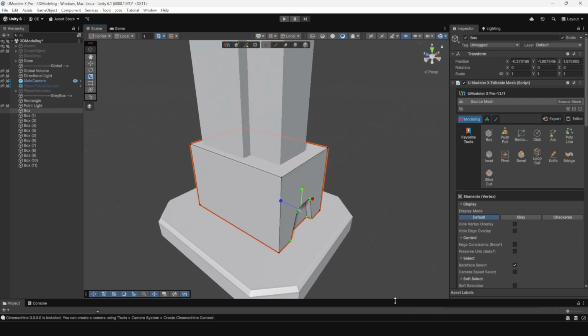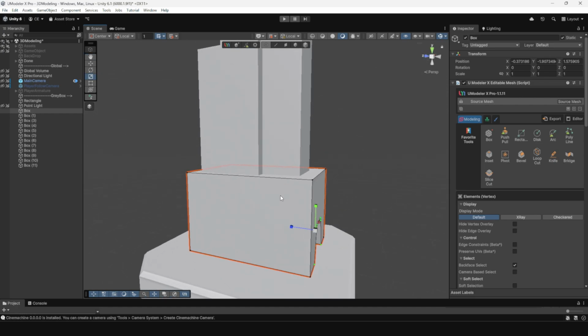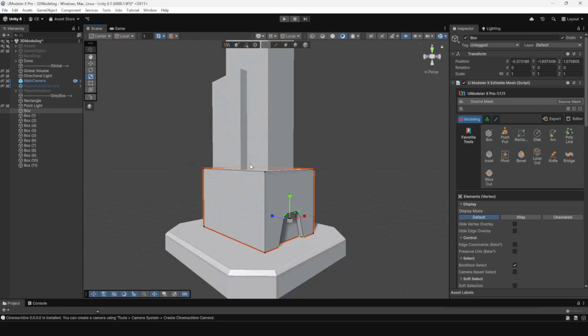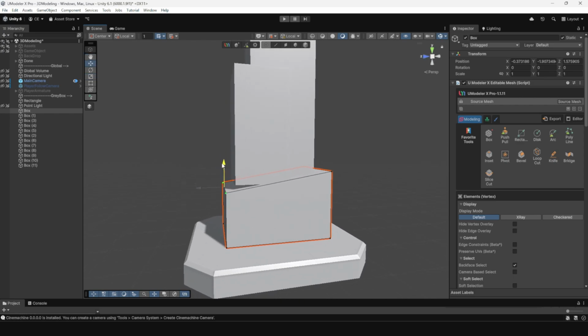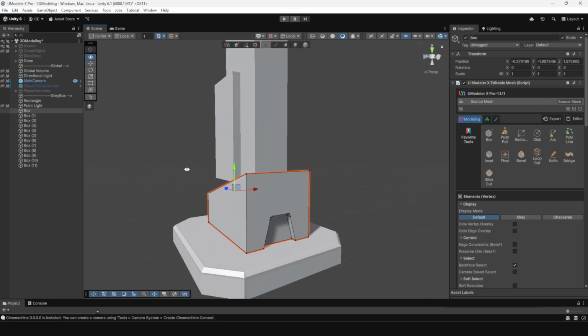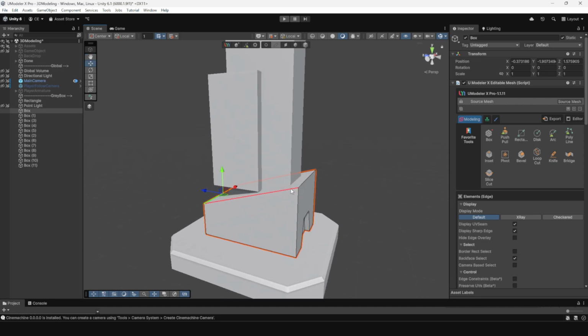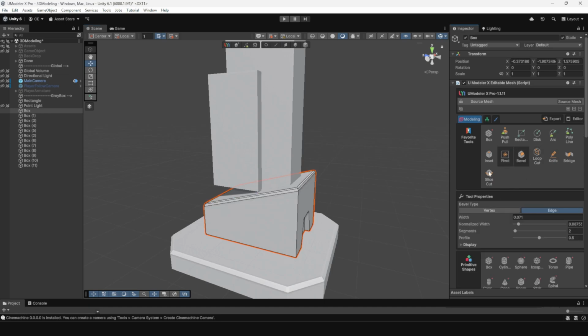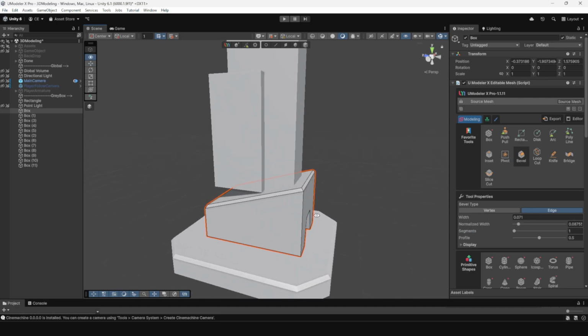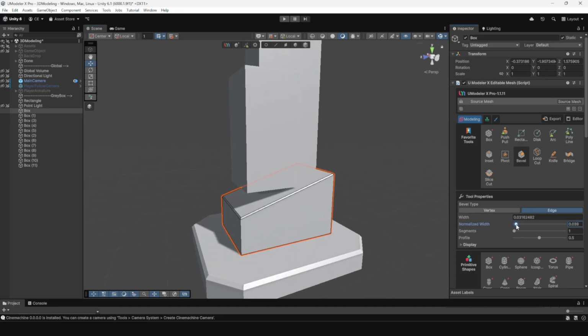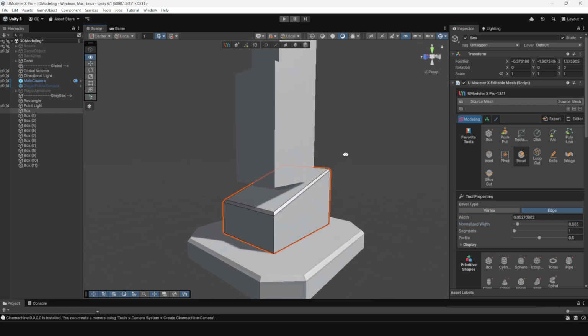All right. So next, what I might want to do is create the back here, and what I'll do is simply bring this down like that just to give it a little bit of slant. And what I want to do is select all these edges, and add a basic bevel to them, and I'll put that on a 1 just like that. I think that is a decent bevel there. I'll just put 0.065. I guess that could work. Looks pretty basic, pretty good.